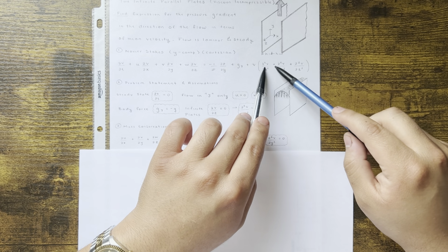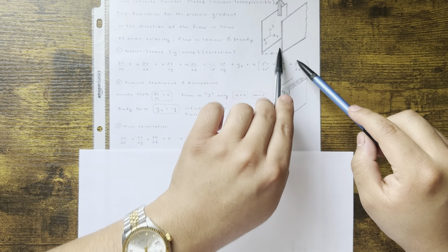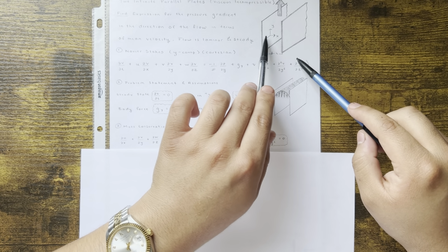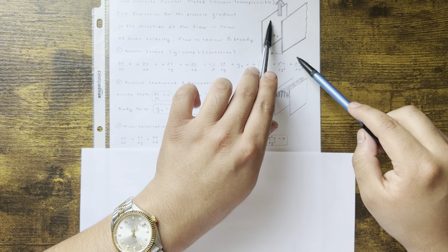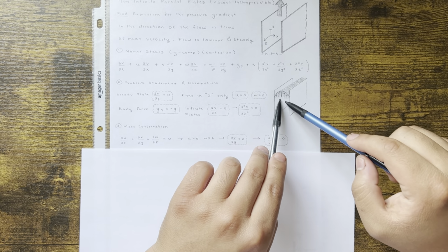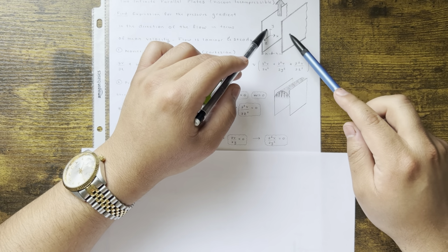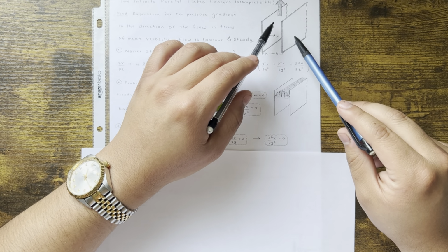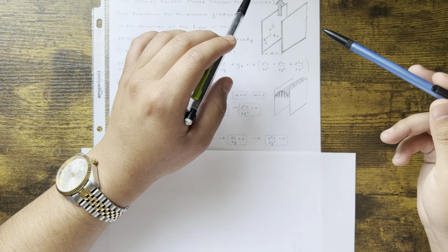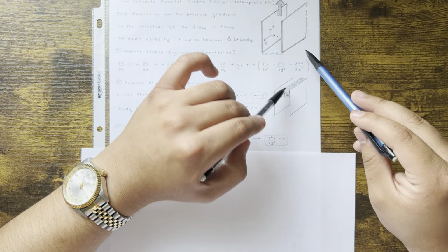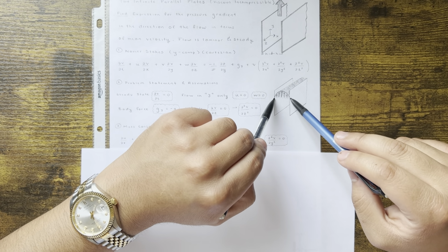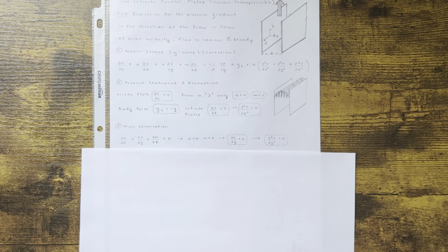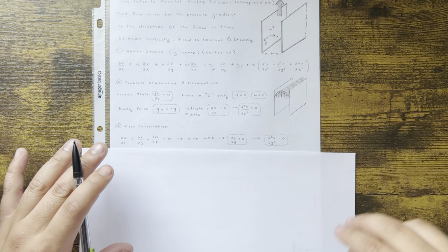And it makes sense, right? It's telling you, hey, how does the y, up and down, how does the y velocity change with respect to x, okay? So it could be very small here, very high here, as you can kind of see. So this was just pure intuition, right? I'm thinking about it, because at the plates, you're going to have no slip. So the fluid wants to stick to the walls. At the center, it's not sticking, right? So at the center, it's the highest, and then because this is no slip, it forms a parabolic shape, okay? So I was just using intuition, understanding what the flow is going to look like.